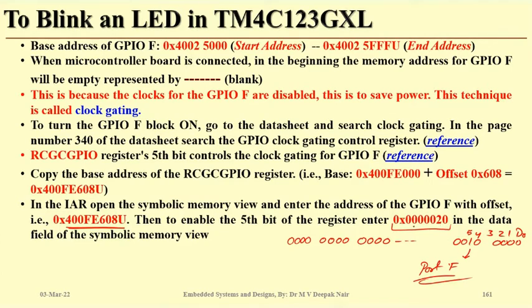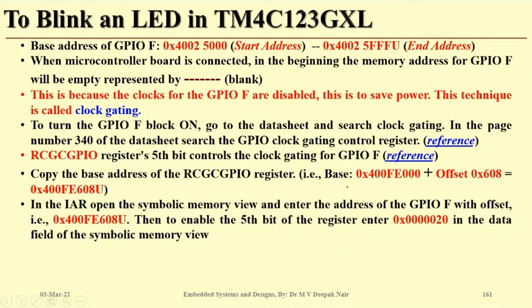So instead of writing this whole number, you can even write 0x20. Okay, and that will enable the clock on port F.